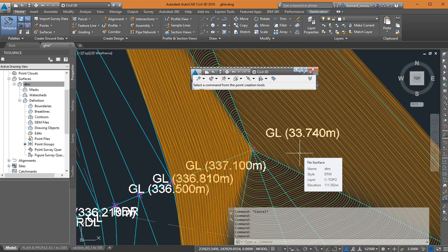I'm saying that AutoCAD Civil 3D has this facility whereby you can have a range. You can have a minimum value or a maximum value, below or above which it will ignore the elevations. So we are going to tell AutoCAD Civil 3D that. That is why it is good that you also visit the site to have an idea of the terrain. Now this particular area is towards Mampong area. That's why you have elevations in the ranges of 300.